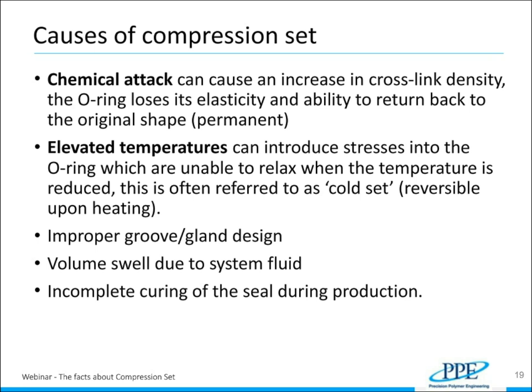And the real one, which we would very rarely see, is the incomplete curing of the seal during production. If a seal was not properly cured or hadn't been produced properly, there was a quality issue there. Residual cross-linking agents that should have been used in the normal production cycle to create beneficial crosslinks that would introduce elasticity have not been. This has not happened, and they are then able to go on and make crosslinks in the compressed state and actually prevent full recovery and full elasticity.